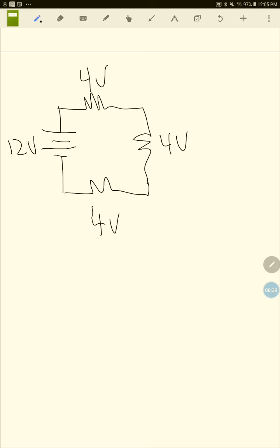And so this time, let's say you're building this circuit in lab, somebody hooks it up wrong, or somebody drops something on the breadboard, whatever happens, and you short that resistor out. Now, usually a short's really bad, but in a series circuit, you've still got some resistance in the circuit, so it's not going to be catastrophic. You're not going to get smoke or fire usually. You could overheat your circuit, but typically what's going to happen here is this voltage is going to drop to 0, because the voltage across a short is always 0. And in effect, what we've just done is we've just taken that resistor out of the circuit.